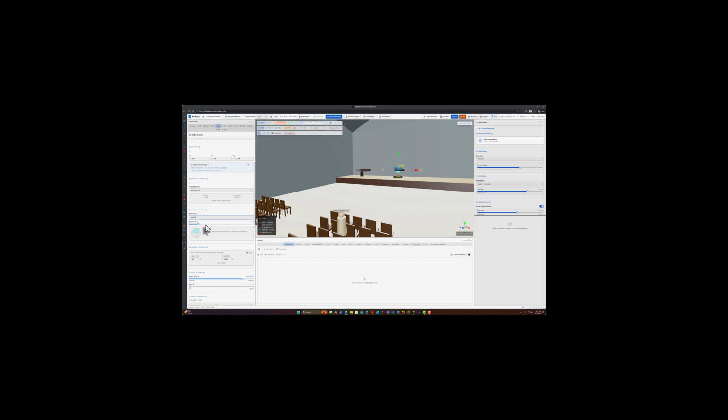Now let's set Q, the directivity factor. Q is a simple way to describe how focused the source is. Higher Q means more energy projects forward, which can noticeably affect clarity, early reflections, and the sense of distance during a walkthrough. For voice, we'll keep Q in a realistic range. Directional enough to feel like speech, but not so narrow that it starts behaving unrealistically.